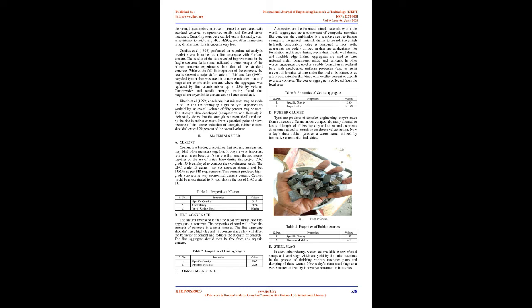Eco-friendly and mass use of waste materials in construction is possible with the use of steel slag for partial substitution of concrete. S.P. Palanisami et al., 2015, indicated the usage of steel slag, a waste of cheap natural materials, as fine aggregate for concrete grade M55, and recommends and accepts the products for use in cement as substitutions of fine aggregates. The partial replacement of natural aggregates allows the gain of compressive, tensile, and flexural resistance and modulus of elasticity of concrete up to an optimum value of replacement.